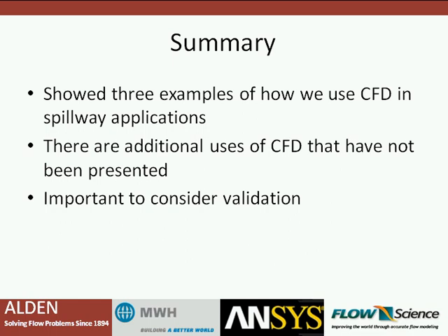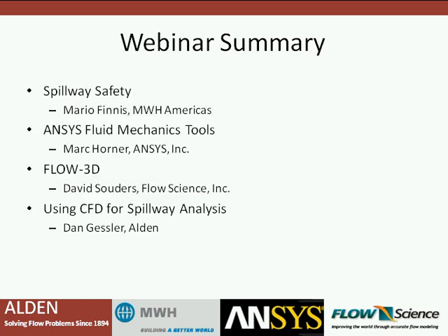And I guess the last point that I would make is that before you even start a CFD model, it's probably good to think about how the model is going to be validated or if it's going to be an unvalidated model. And certainly unvalidated models have their value in the industry, and I don't want to take away from that. But at the same point in time, we want to think about how we can validate the models whenever possible. So with that, I'd like to thank everybody for signing on and turn it over to Dave.